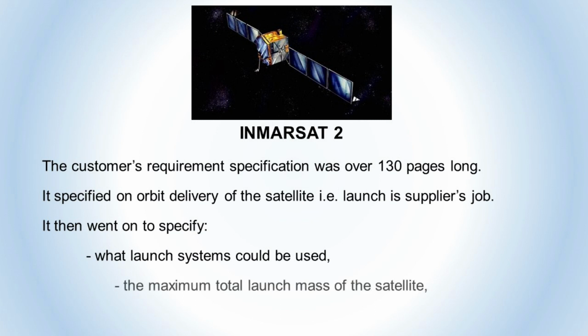But then they set the requirement on the maximum mass of the satellite. It was almost as if they didn't trust us to be able to read the launch system user manuals, which define the maximum weights. And in reality, they were different from launcher to launcher, not just the single value defined in the specification. And they need to be different as the propellant needed by the satellite itself was different depending on where the launch site was located. So not only was there no need to specify the maximum mass, they did it in a way that actually hindered and constrained the design unnecessarily.